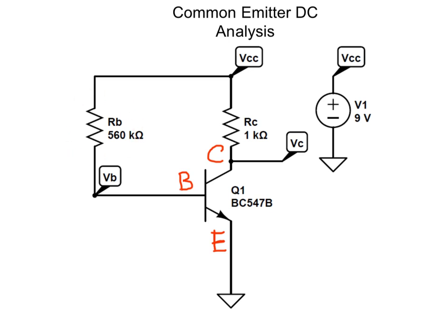The resistor RB sets the base current which flows into the base terminal of the transistor Q1. Let's call this current IBQ. It is important to realize that this base current IBQ does not change over time and is therefore known as the quiescent base current. The transistor Q1 then amplifies this small base current. The amplified current flows into the collector through the collector resistance RC. Let's call this current ICQ.